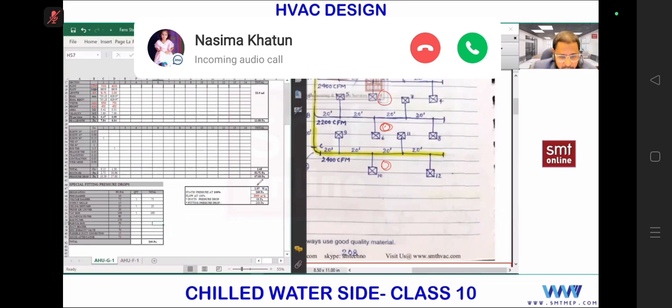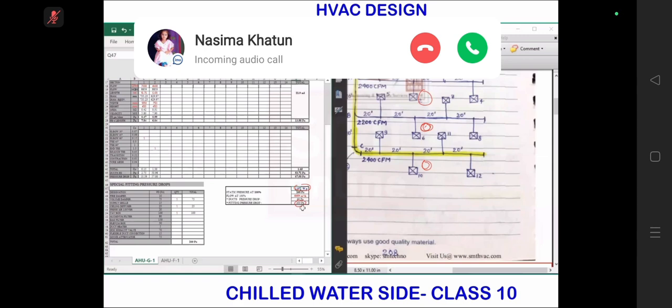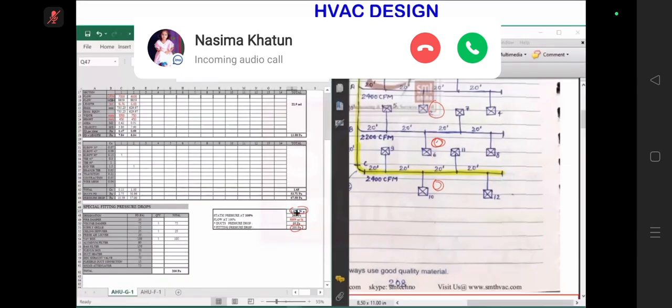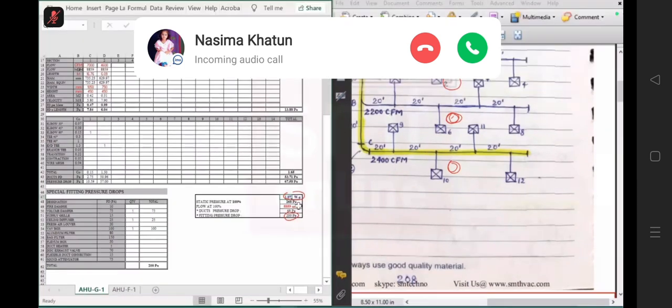You see, 1.07. First you will get in Pascal, and here you can find the conversion. When I click here, you can find the formula Q48 by 249. Now you can take 250. Q48 is here 268. 268 Pascals. 268 Pascal, if you convert it to inches of water gauge, 268 divided by 249, 1.07. Got it? Simple. So this exercise is very simple.